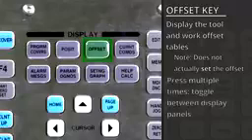Pressing the key multiple times will toggle between display panels, making either the tool offsets or the work offsets the active panel. On newer Haas control software, the active panel is designated by a white-colored background, while the rest of the display panels have a blue-colored background.